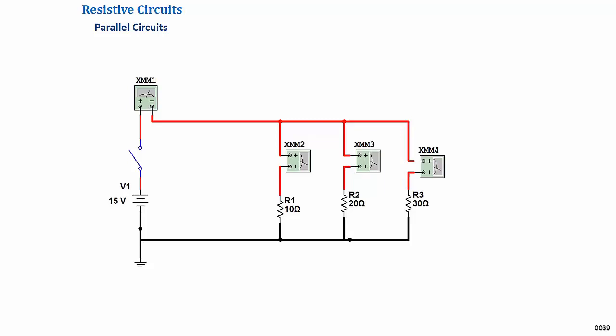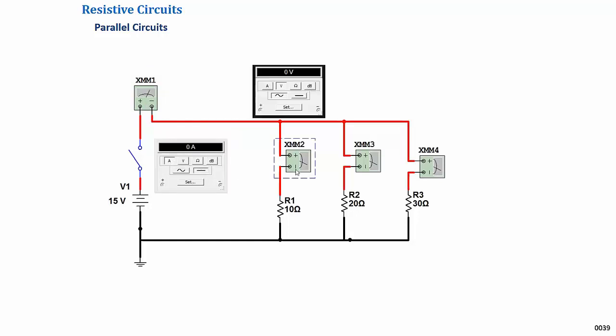This video clip is a simulation of the example and shows how the circuit and branch currents would be measured in practice. The DMM is connected to the main supply line, and one DMM is connected in series with each branch resistor.